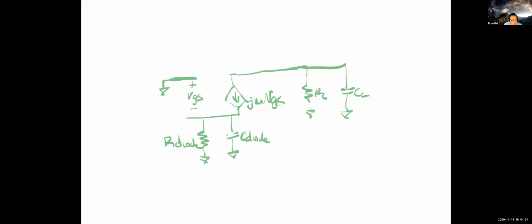All right, so a couple of things that I've done. All of the independent voltage sources have been shorted, so things like VDD got shorted. Independent current sources got opened, so you'll notice that I-bias is an open circuit in this. And let me make sure if we're supposed to include, neglect R out, the body effect, and all device capacitors other than CGS and CGD. Okay, so we do need to include them.